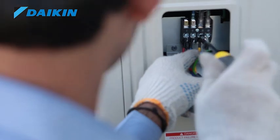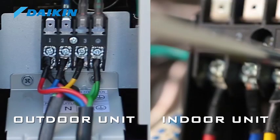Now connect the other end of the electrical cable in the outdoor unit. Ensure the same sequence and color codes are properly followed when making the electrical connections in the outdoor unit.